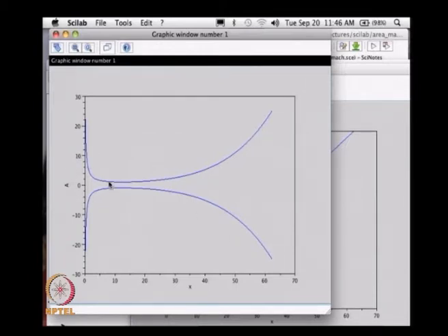So, what do we have over here? We went from 0.98 and then we went to 1.02. So, what happens in this region? As you can see from this diagram also, this is basically the least area in the entire distribution. So, this is where it goes through a Mach 1. It goes through a Mach 1.